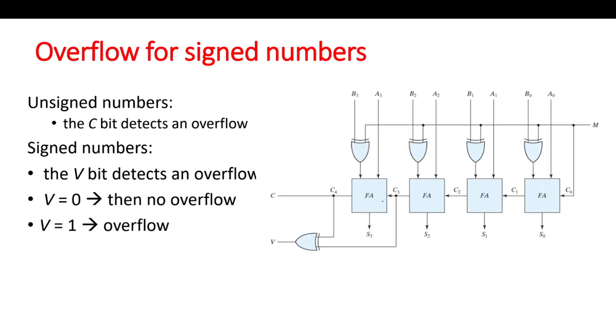So we are taking the XOR of the previous carry and this carry to get the carry out. This will not have any significance. And we are taking the B's complement. So A minus B is the 2's complement. And for 2's complement, this mode will select whether it is subtraction or addition, and plus 1 for the 2's complement.